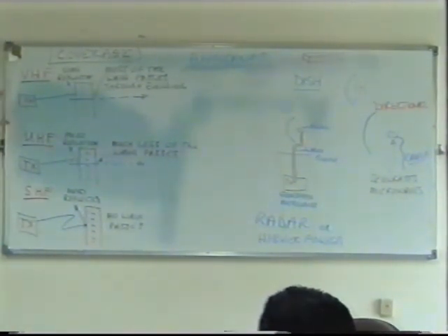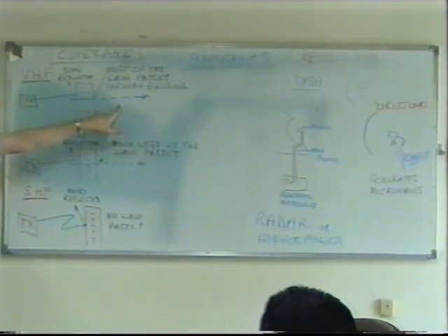Basically I split it into three basic areas here, VHF, UHF and SHF, and we see the effect of any obstacle, which could be a building or a hill or a mountain, anything physical between us, and we can see the differences. VHF is the best for coverage.